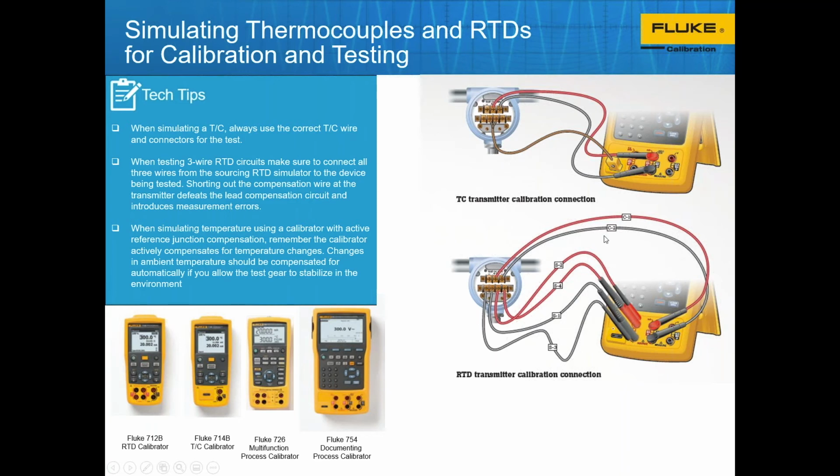The reason this is being done in the first place is we are actually taking a measurement between the probes and the wires and determining the resistance of this test lead and subtracting it from what's happening here to here. So effectively, we're eliminating or removing the test lead's resistance from the overall resistance being sourced into the transmitter. So again, very, very important to keep in mind.